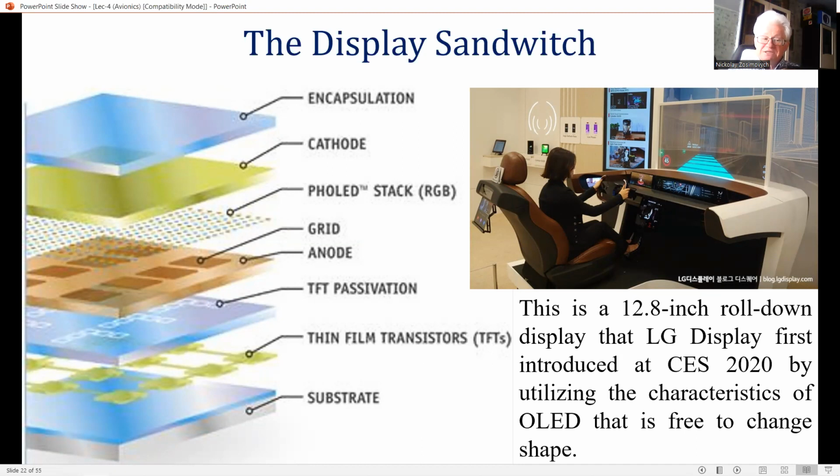They are an emissive display with an inherently wide viewing angle and crisp display characteristics. They have a fast response time of 10 to 20 nanoseconds and have a wide operating temperature range when properly packaged. They have active matrix addressing like AM LCDs and can have high brightness. They are thin and do not require an illuminating light source like the AM LCD, and thus enable a slim flat panel display to be achieved.